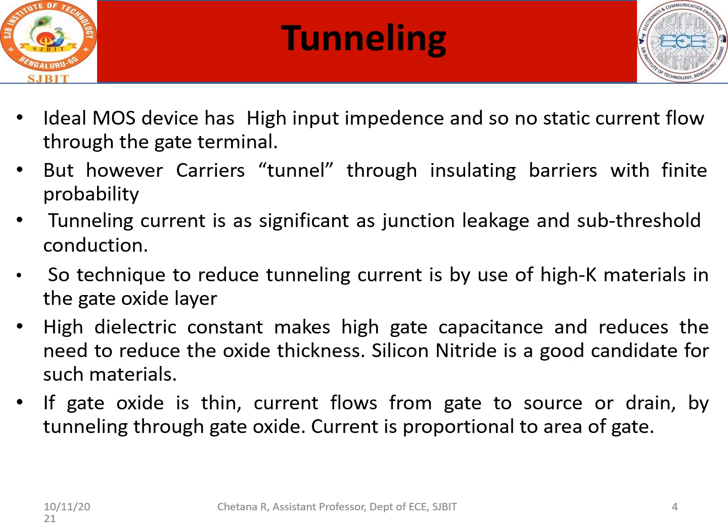How is this possible? Use a better dielectric material which has high permittivity. High permittivity means it restricts the charge carriers from sneaking inside and conducting. Therefore, a high dielectric constant gives high capacitance and reduces the need to reduce the oxide thickness, because we know the oxide thickness is very thin.